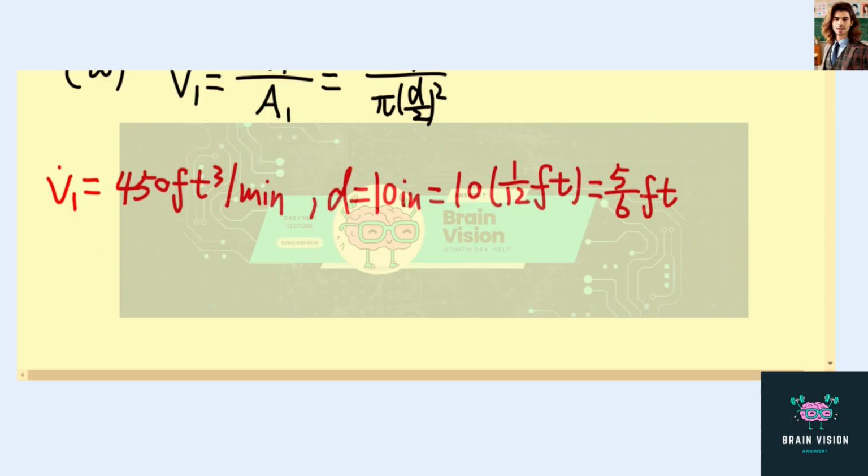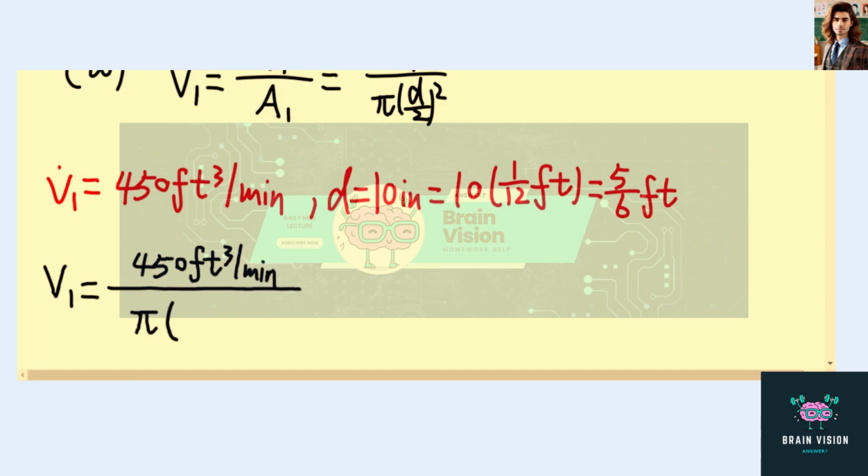So now let's plug back into the equation to determine the inlet velocity, which is equal to 450 feet to the power 3 per minute, and then divided by pi times 5 over 6 feet over 2 to the power 2. And this will give us the inlet velocity is about 825 feet per minute.